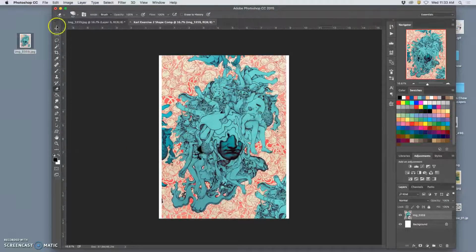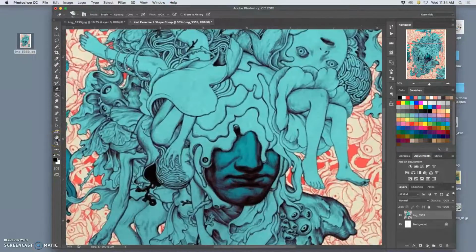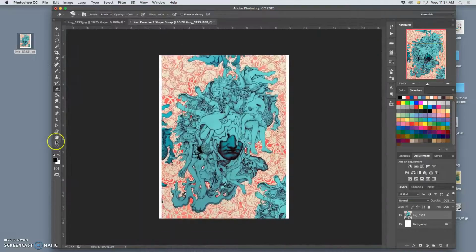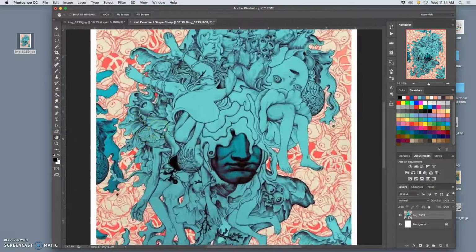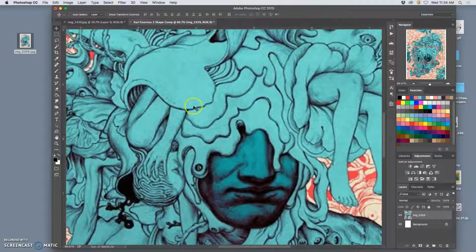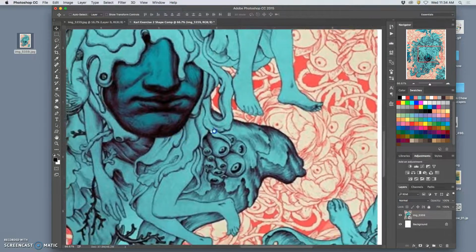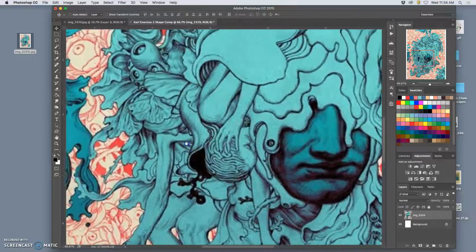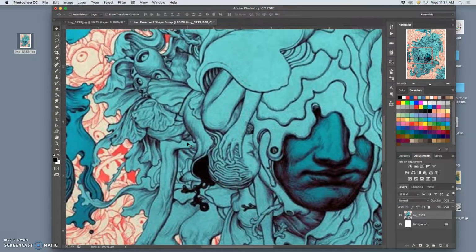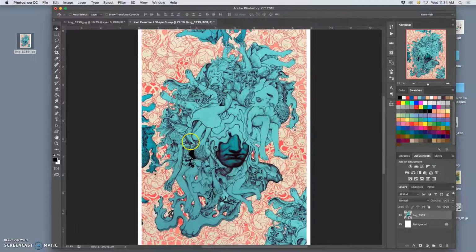A big blue oval. So I'm going to go down from all these selection tools we've been using, down from the bottom basically, and above the magnifying glass, which we just use shortcuts for, Command plus, Command minus, the hand, which we can use a shortcut for too. So instead of using the hand, if you just hit spacebar when you're zoomed in, it will automatically make it the hand, and then you can click and move around when you're zoomed in. That's going to be helpful to you. Command 0 is a nice shortcut for fitting everything on the screen. So we don't really need these two at all.